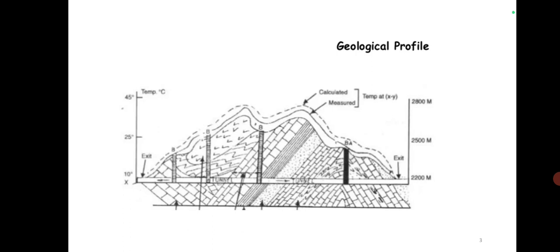The photograph you see is the geological profile, and it is the most important geological record available, and the guideline for tunneling. It provides information about the location, the depth of boreholes, the type of rock, then structures, as I told you, the secondary structures like faults, and also the groundwater conditions, the hydrological conditions, and the ground temperature.